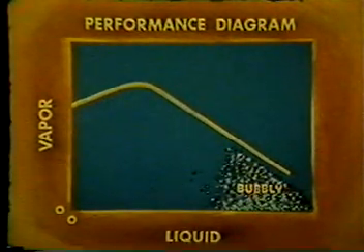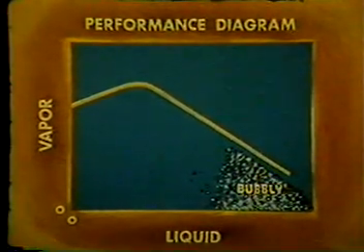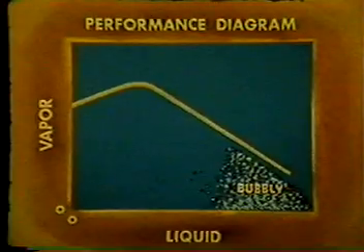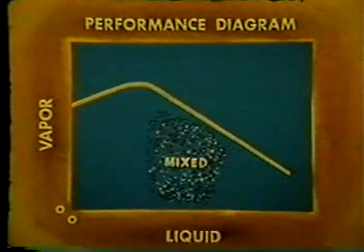The bubbly regime exists at the high liquid rate region. Here, the vapor-liquid contacting is taking place under bubbly or frothy conditions. This appearance is typical of high-pressure distillation. The intermediate region is the mixed regime, where the two-phase phenomena cannot clearly be defined as either spray or bubbly.